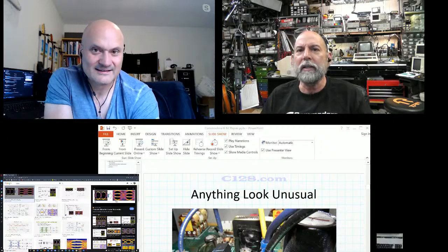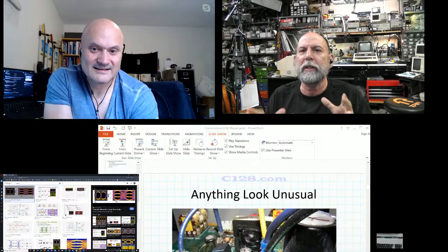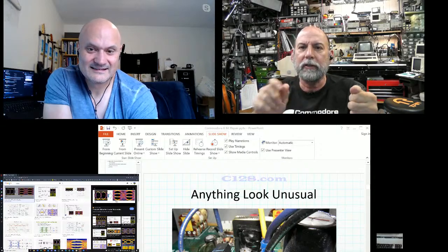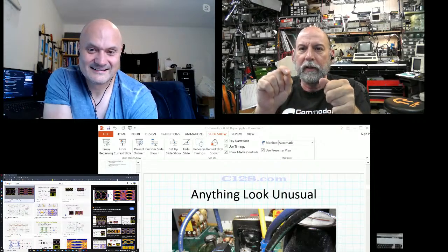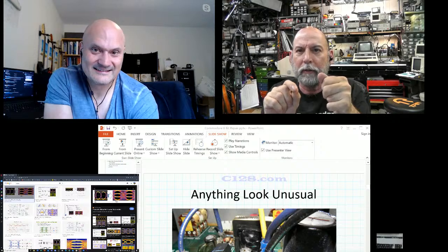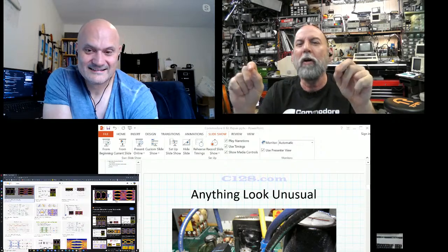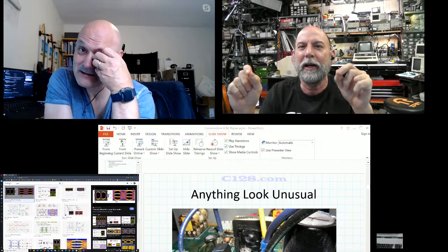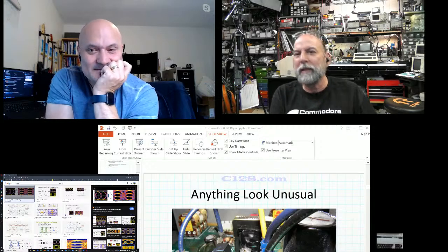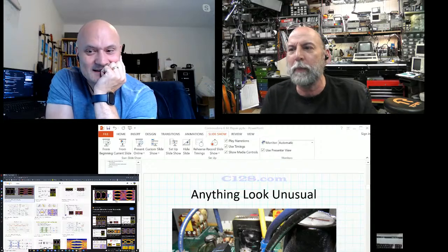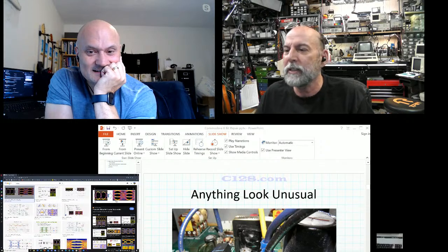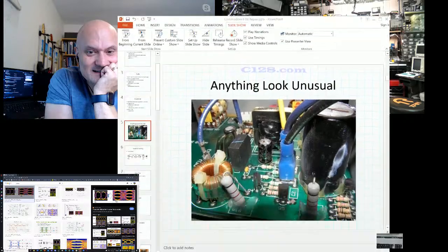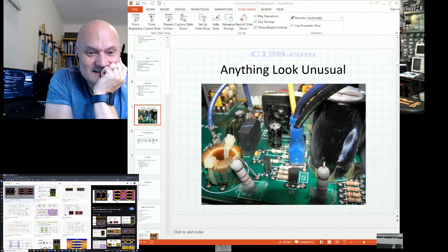And I found that I could sit there and fix half of the units without even turning them on by staring at every single cut job. I looked at each one and verified, and often the cut would be on the trace next to the one it was supposed to be. Or the jumper almost went to the right pad, just not quite. So I would get a big leg up on all the other technicians. By 9 o'clock, I'd fixed half my bin by using my eyesight. So visual inspection is real important.